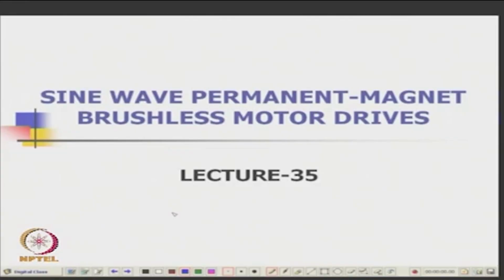The another variety is a conventional synchronous motor, or it is a sine wave permanent magnet, again a brushless motor. So, rotor will be same. In fact nowadays there are a lot of configurations of permanent magnet rotors, they are surface mounted. So, you have a mild steel, then you mount the magnets on the surface, or you can have the embedded magnets, you can put it inside a ferromagnetic structure. So, it will provide the proper magnetization.